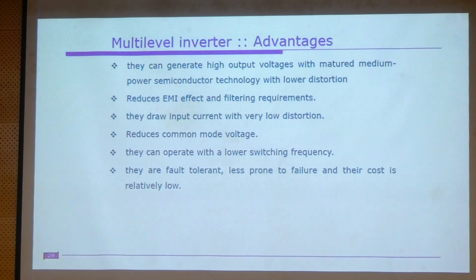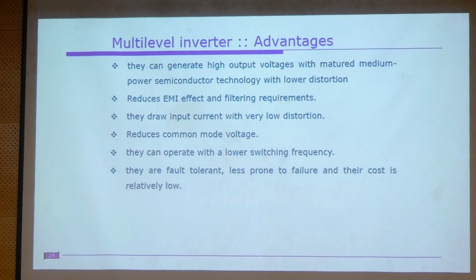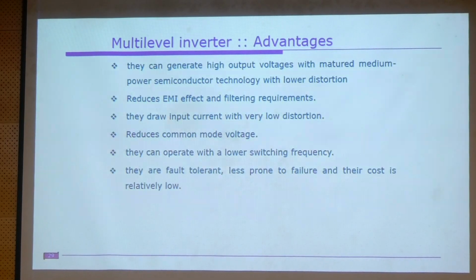Understood? So that's why we need to avoid or eliminate the common mode voltage. Eliminating common mode voltage is itself a major topic, especially in motors. The good thing is that when you are using multi-level inverters, the waveform is very close to a sinusoidal waveform. So if we add all the phase voltages, the magnitude also will be reduced. So we can naturally minimize it. Without any additional controller we cannot completely eliminate the common mode voltage, but we can drastically reduce it. Right?